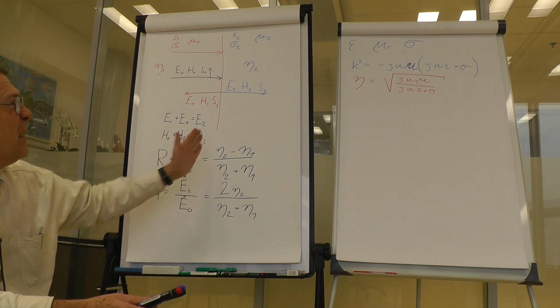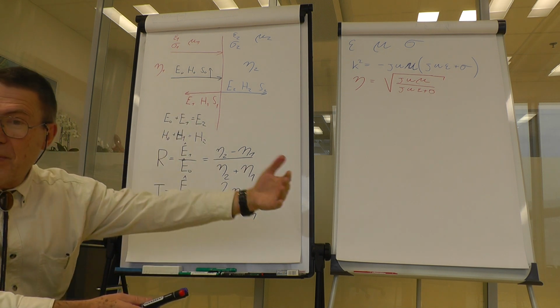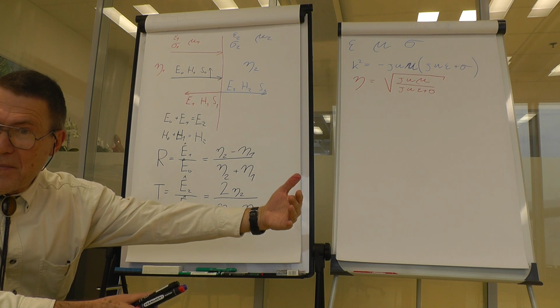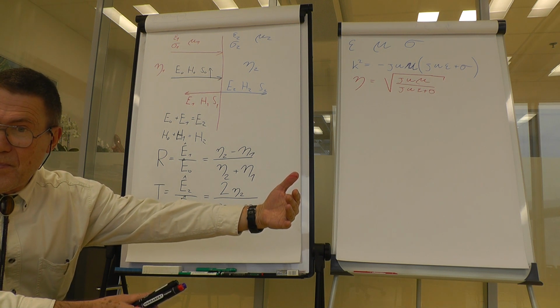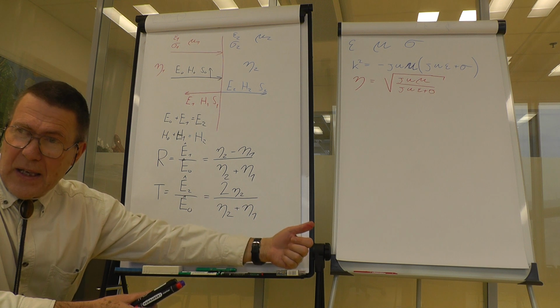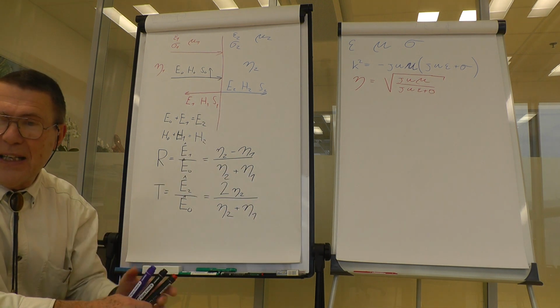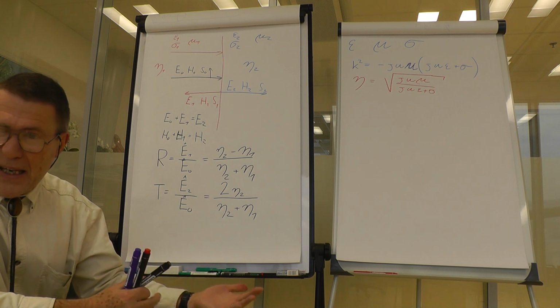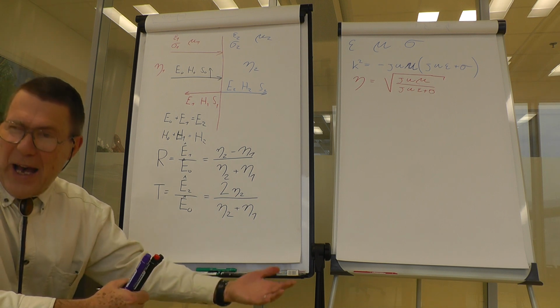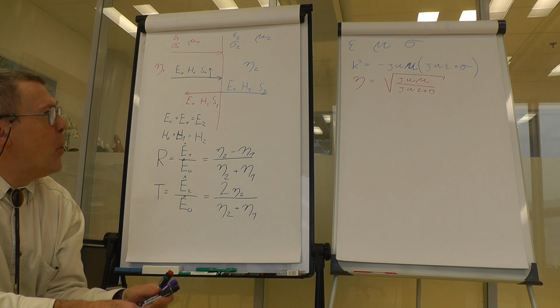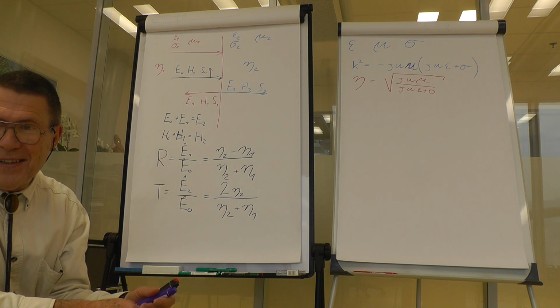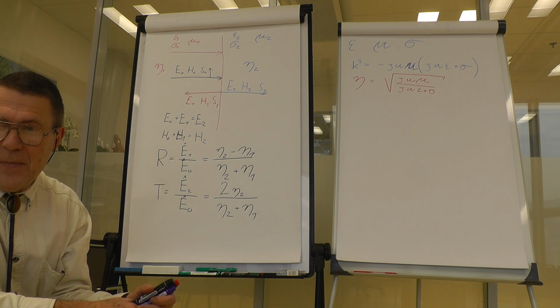Now with increasing frequency this is no more possible, and in fact what we can measure is a reflection at the boundary and a transmission through some depth of the material. As the reflection has both a magnitude and phase, and the transmission has both damping, that is magnitude, and phase, we have four independent numbers to be achieved.